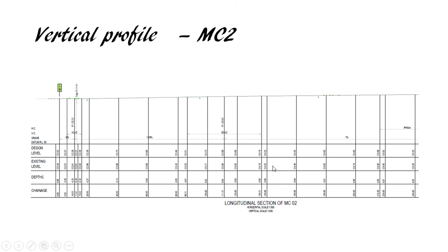So basically I have talked about the Austroads design guideline for vertical grading. The minimum grade has to be 1%, which we have provided, and the crest curve criteria which I described earlier has been applied to the vertical profiling. You can also have a look at the video provided earlier; the description is below.